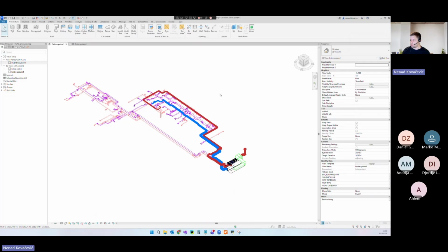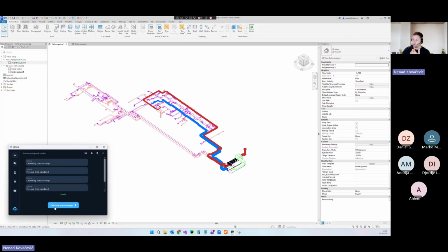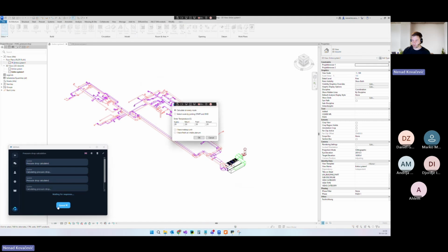So that final option with plenum box. Every time, because over here we will set the colors, this is, I think, okay when you're calculating the pressure drop and you want to see the critical path. But if this is some working view and you just want to reset the colors, you can just start the pressure calculation again. It will automatically reset the colors, because maybe you now did change the pressure drop on some elements, and now the critical path will be some other path. So, okay, let's again use the air handling unit for calculation of everything.